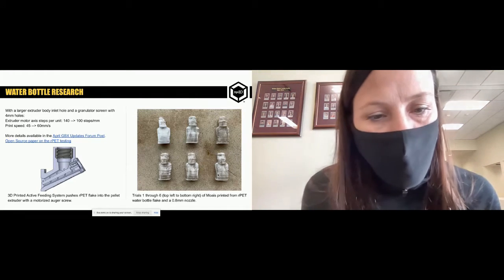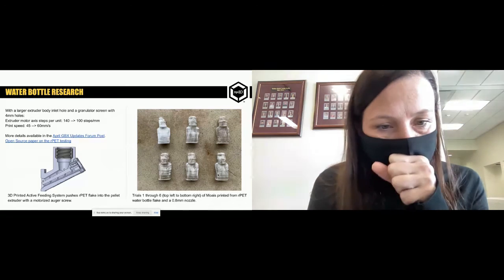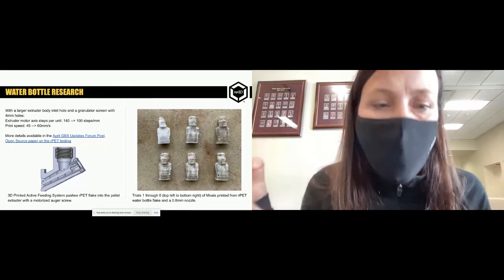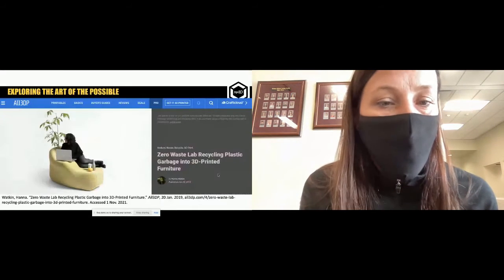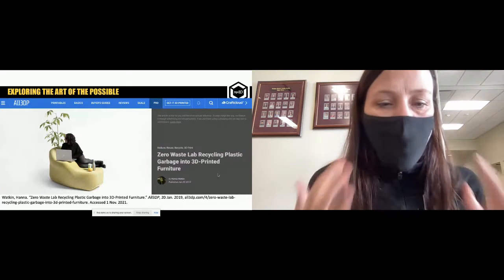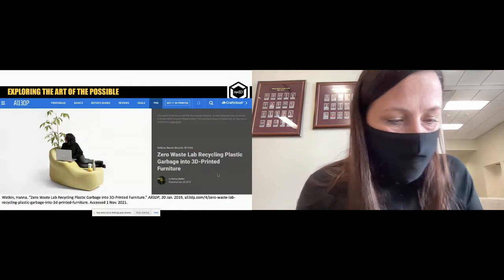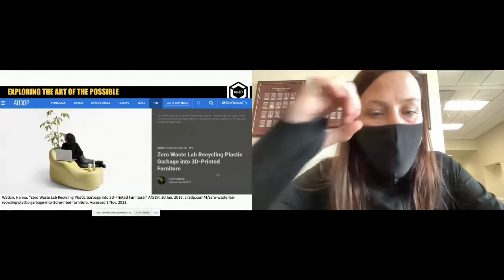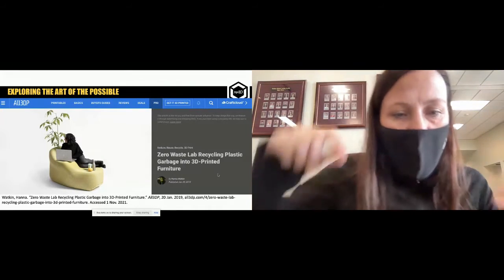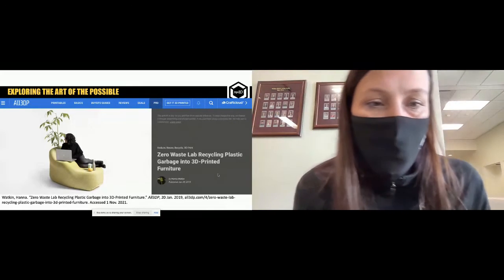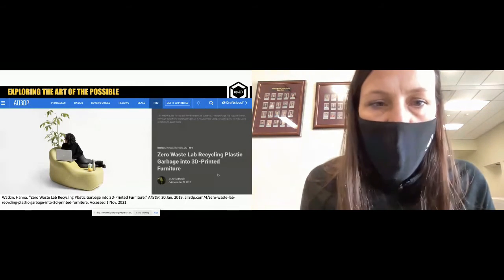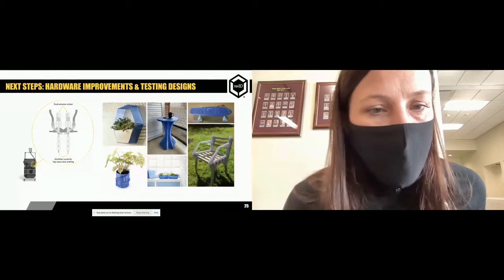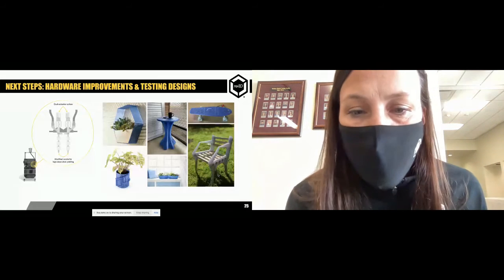So we started to work a lot, particularly on assistive feeding mechanisms to help cope with challenges with flake. We have some research right now around what we call a crammer, and we're also looking at using vibration motors as well with the University of Texas. How a lot of our peers have overcome this is by focusing on larger nozzle sizes, right? By printing with a bigger bead, sometimes you can overcome some of these challenges. And then also looking at things where you can do that continuous line, whether you're using a gantry system like ours, or there's also a need for a dual extrusion system. That's not something we've been able to dedicate research to, but some of our peers are thinking about.